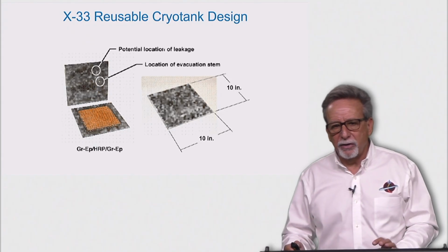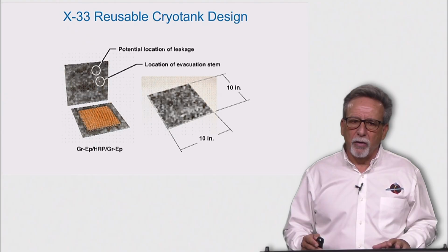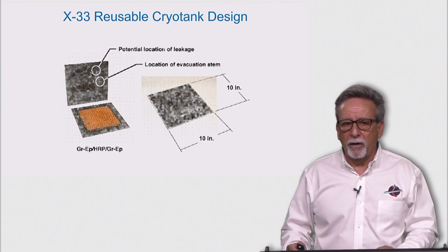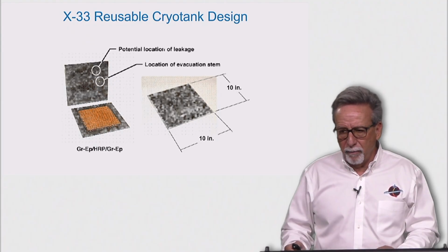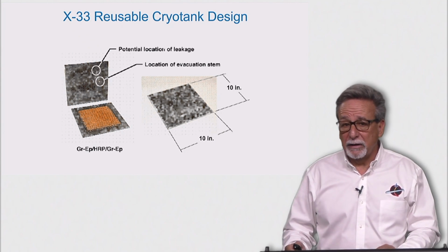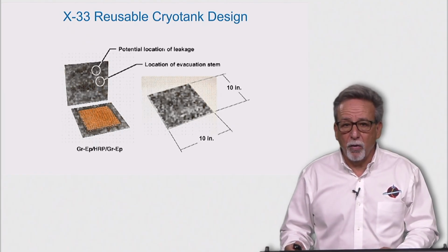The slightly larger test specimen was designed to include a conventional honeycomb core closeout and mechanism for actively evacuating the core. The primary purpose of this test article was twofold: to determine the feasibility of actively evacuating and maintaining a vacuum in graphite epoxy composite bonded sandwich panels, and to test several methods for monitoring leakage and/or ingestion of air or hydrogen into the honeycomb core.